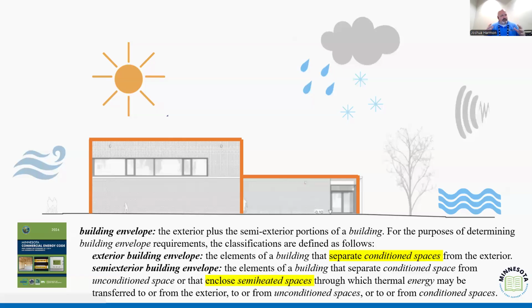We might look at glass as a concept or an exterior cladding, right? Well, that has a function that's different than the insulation in the wall, right? If we're thinking about the shell, let's build a big old building, a strip mall, and we're going to put tenants in it. Well, that exterior envelope of the building is not just going to resist a little bit of rain and snow. We also want it to control the air within that space.